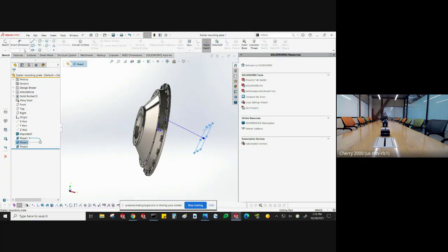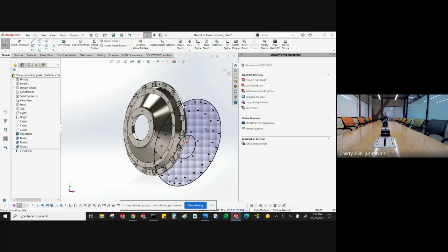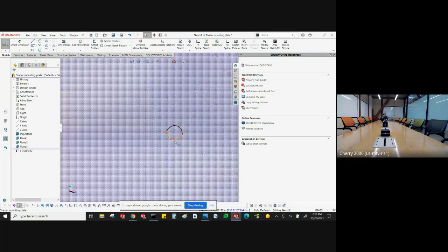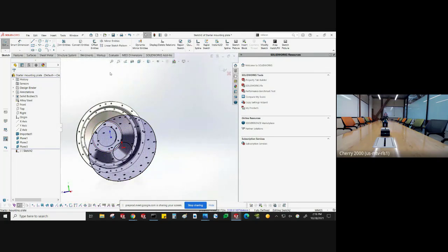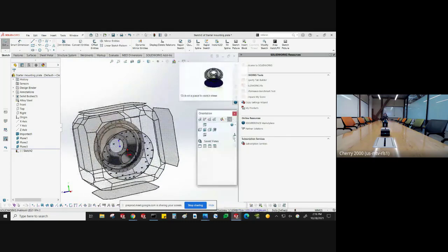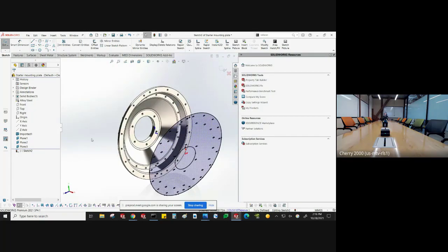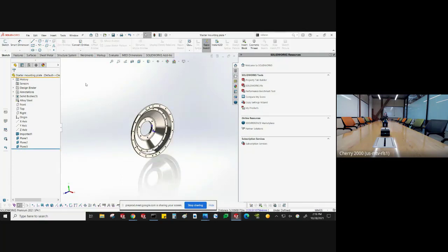So if I were to open a sketch on this angled plane and do the same thing, rather than being true circles, which was what I got when I shone a light through the holes looking straight down at them, now that it's at an angle, I get these splines that are elliptical. But if I go normal to my sketch plane, that's exactly what that part looks like if I'm looking at it from that plane. So it's just an easier way to grab geometry off of something. It's, again, in your usual convert entities, just in that pull down.